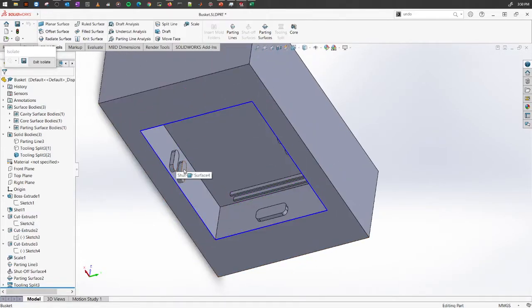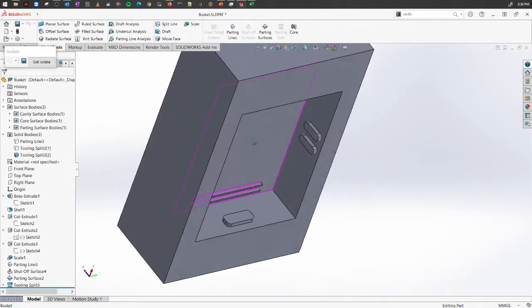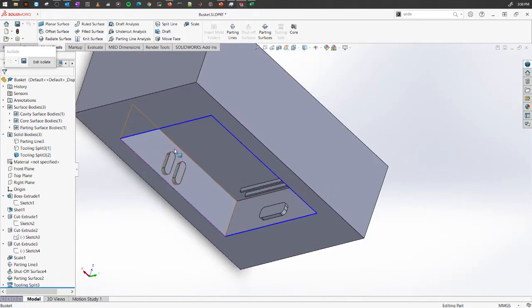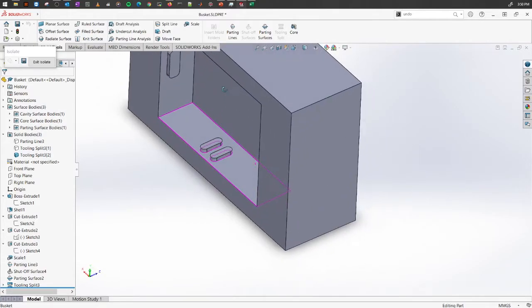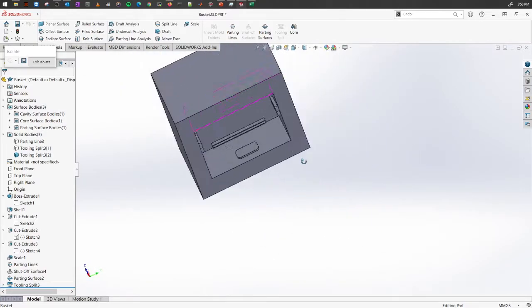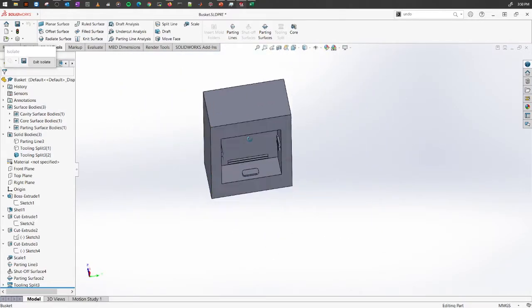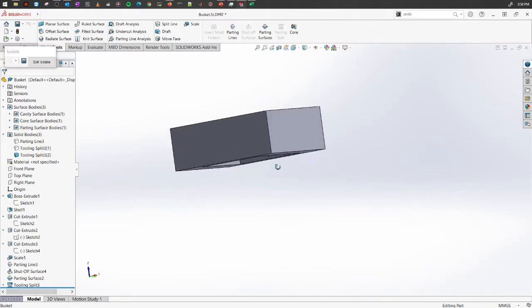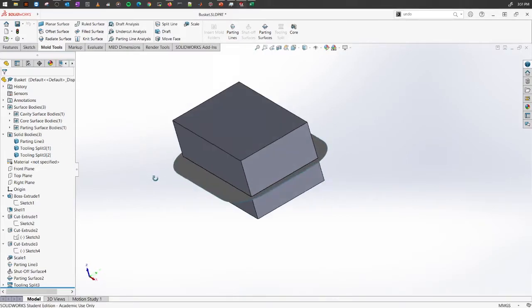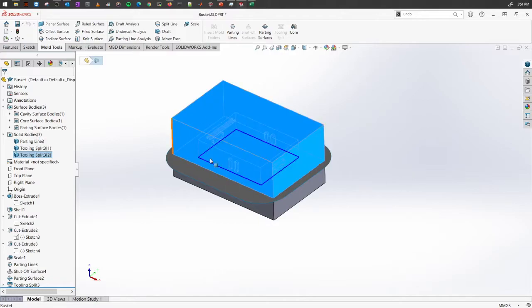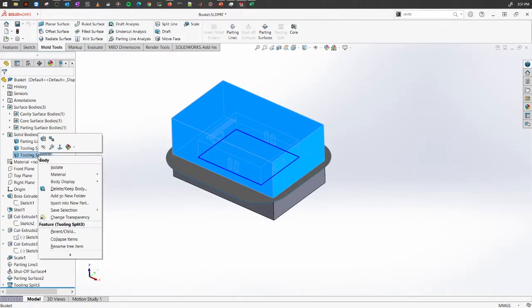But this side, if we create this, pulling out the design will be a little tough because it's gonna get stuck here. So we need some movable parts around these regions so that we can easily create our mold. Thus, we need to create our core design. Okay, so let's exit isolation and hide this top portion of it. Right click on it and hide.